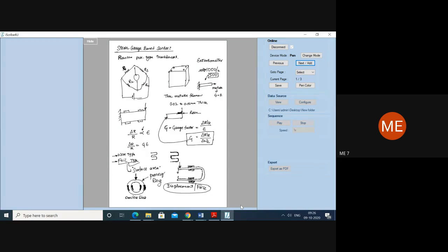Now to summarize, today we have finished with the light sensor. The concept of the light sensor is the photoconducting or photoelectric effect. Under the photoelectric effect, photon energy is converted into electrical energy. So there are photoemissive sensors, photoconductive sensors, and photovoltaic sensors. Later on we discussed the strain gauges, which are mainly used for measurement of force and torque. I think we'll stop at this stage.